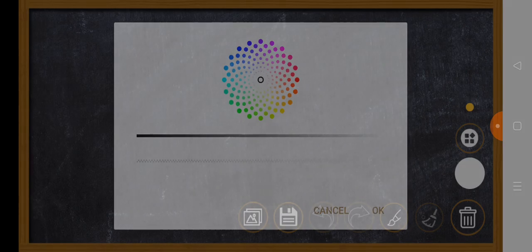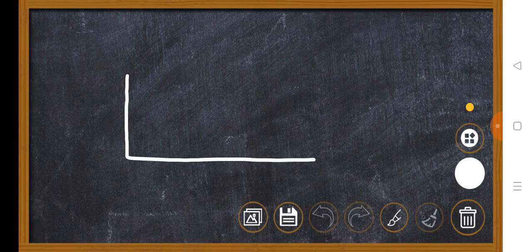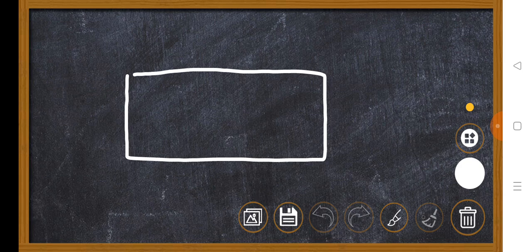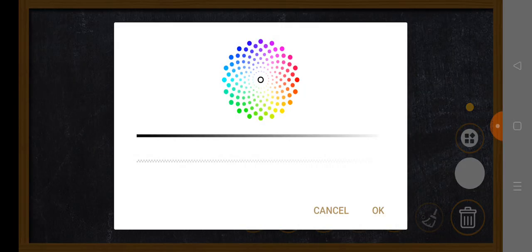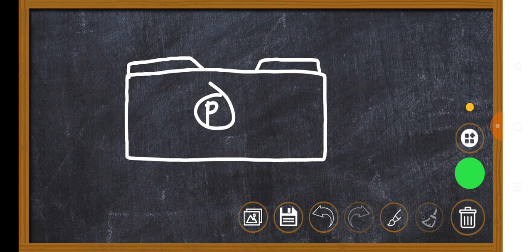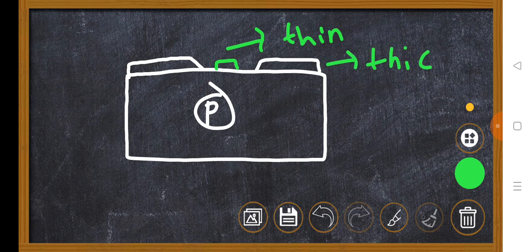Now if you observe how this structure will look, this is your substrate of p type, and this is your thick oxide with a window opened in the oxide. Here I would like to use some other color for indicating this is your thin oxide. I hope you are clear. This is your thin oxide. This is your thick oxide. This is known as growing a thin oxide, or you may call it a gate oxide. Is it okay? Then after that, remember a very important point.